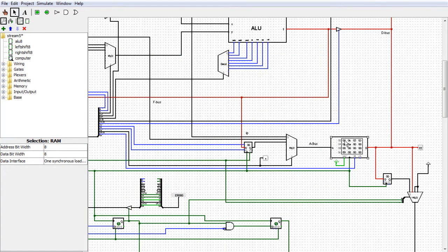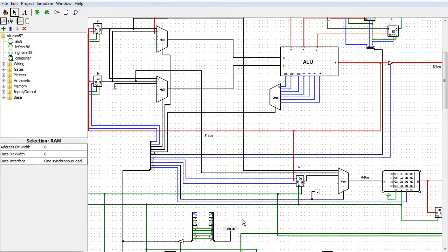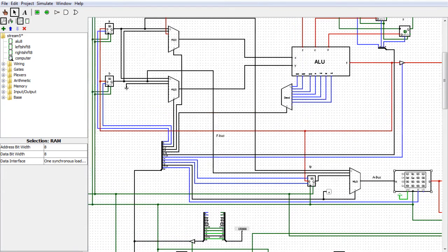It's very simple. It puts the address 0C into register B, then loads the data from that address into register A, and then stores. Then it loads address D into register B, and again stores the contents of A into the memory pointed at by B, which is D. Anyways, you'll see what happens when it happens. Let's try this out.